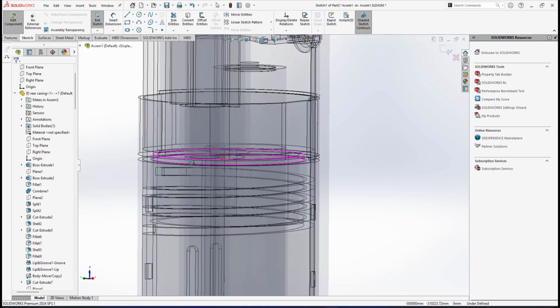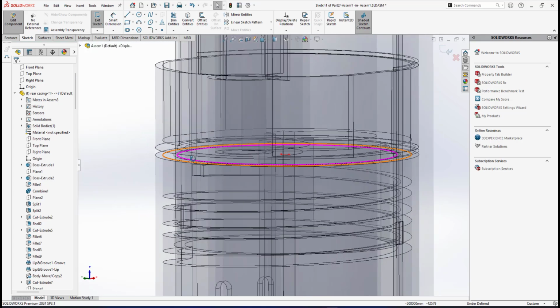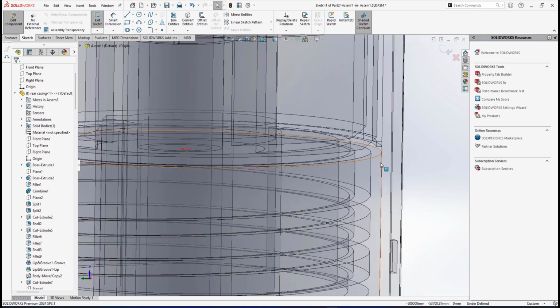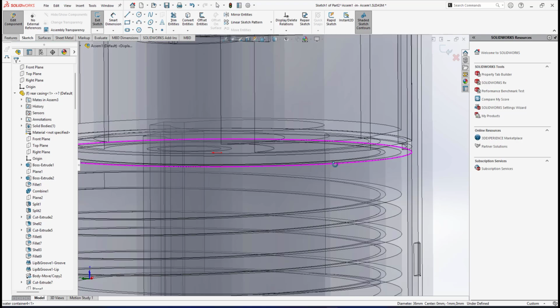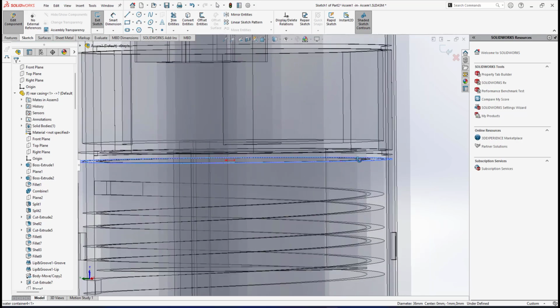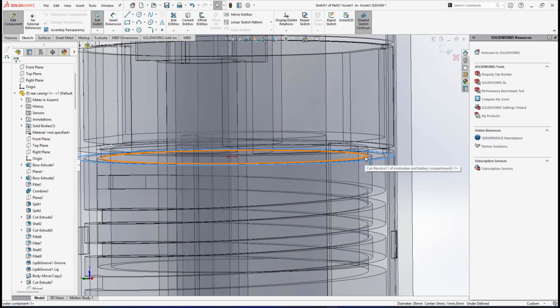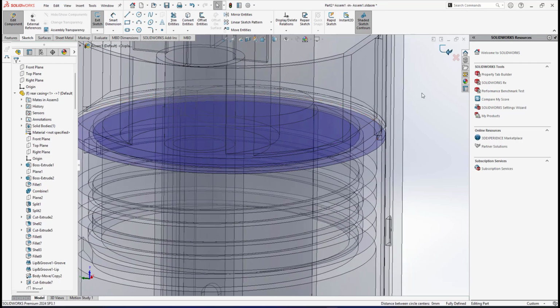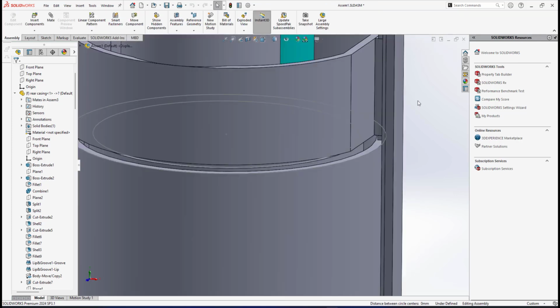So I'm not on that plane, so I need to trace the size of the outline for me to create the water container. So the line will be the water sealant, to create the water sealant or the rubber sealant, the silicon sealant. This face, and carefully select these edges, the inner edges. Hold on the Control key. I already selected that to circular edge, then convert entities. Also I have the outline. So I will exit this sketch, then I will exit edit part mode.